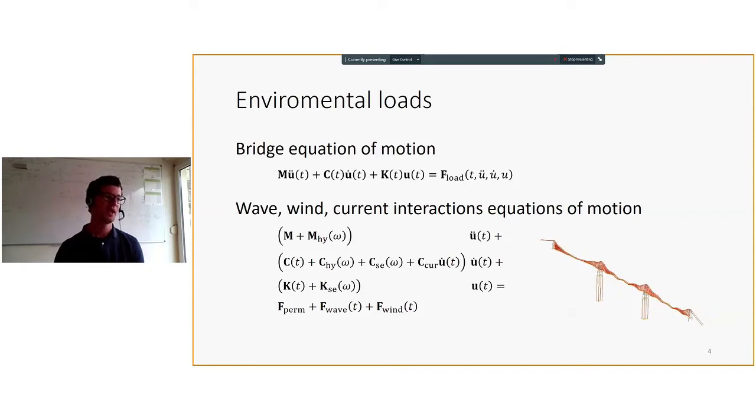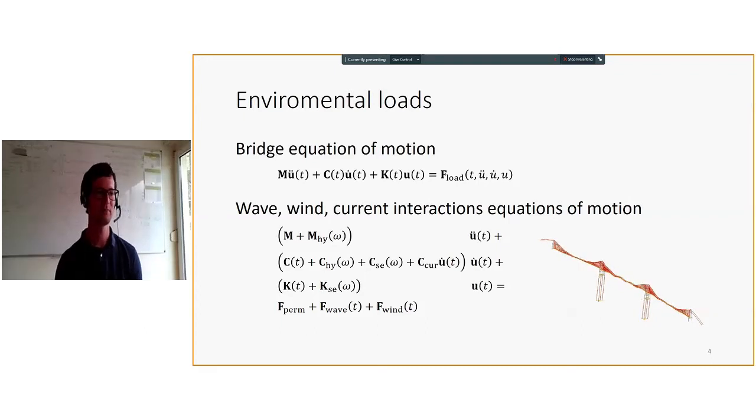In general, those bridges are nonlinear, so therefore they have to be described with a time-dependent damping and time-dependent stiffness. And as well, they have different load components, which are time-dependent: acceleration, velocity, or displacement. So you pretty much have everything on those bridges.